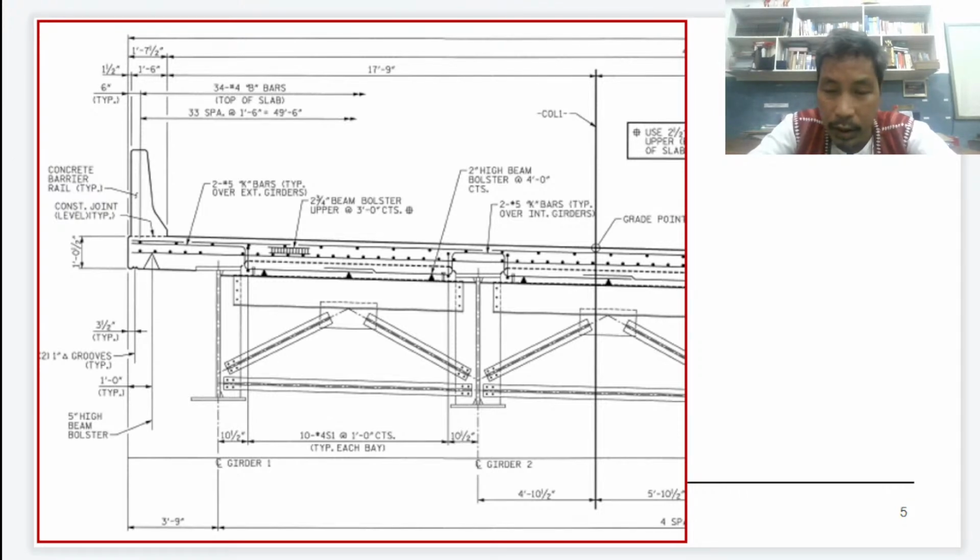But I do not have the document, but I have the video. And the structure failed. It fell down. So, I showed you the remaining reinforcing bars. The splicings remain beautifully aligned. Beautifully aligned, but that is not correct. That is not a correct alignment of splicing. Probably one of the reasons why it actually fails.